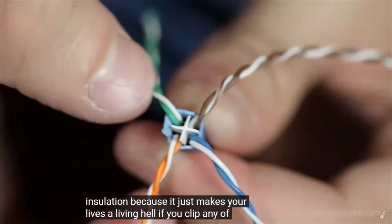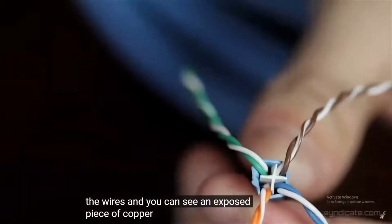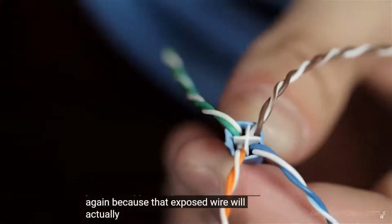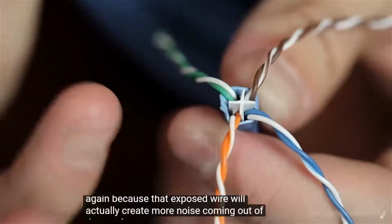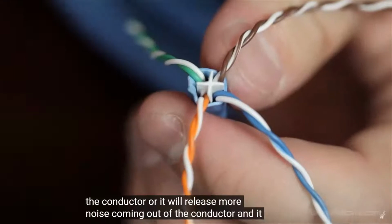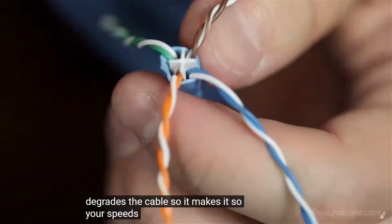If you clip any of the wires and you can see an exposed piece of copper, cut your cable and start again, because that exposed wire will release more noise coming out of the conductor, and it degrades the cable, so it makes it so your speeds won't be as high as you want them to be.